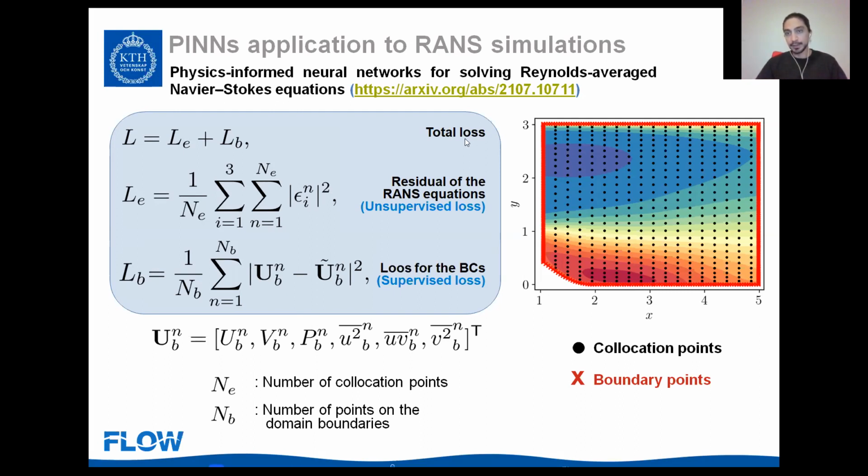Yeah, it's definitely true that it's a very ill-posed problem. So guiding the solution in that way might be tricky, but this work is just an introduction that it is possible to use some data. We've done this for heat transfer problems where we don't have boundary conditions, and you can have a few thermocouples that give you that. If you try to generalize this, it's a matter of surface to volume information. You have surface information that you convert to volume, and the question is, what is the threshold? For this case, it works. It seems to work well, right?